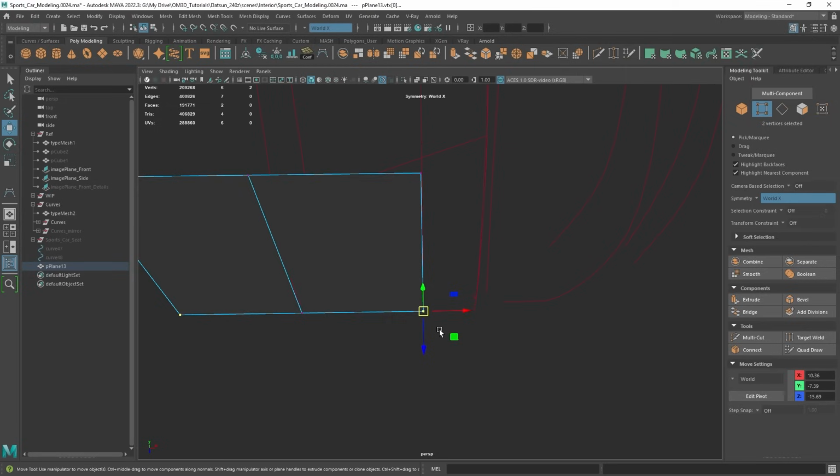Now the way to do this is a little bit tricky because you'd think you just want to left click and move it and it'll snap. But you can see if I'm holding C on my keyboard for curve, it starts to highlight curve mode here. So you can actually just enable this if you know you're going to be doing this and just kind of work on that.